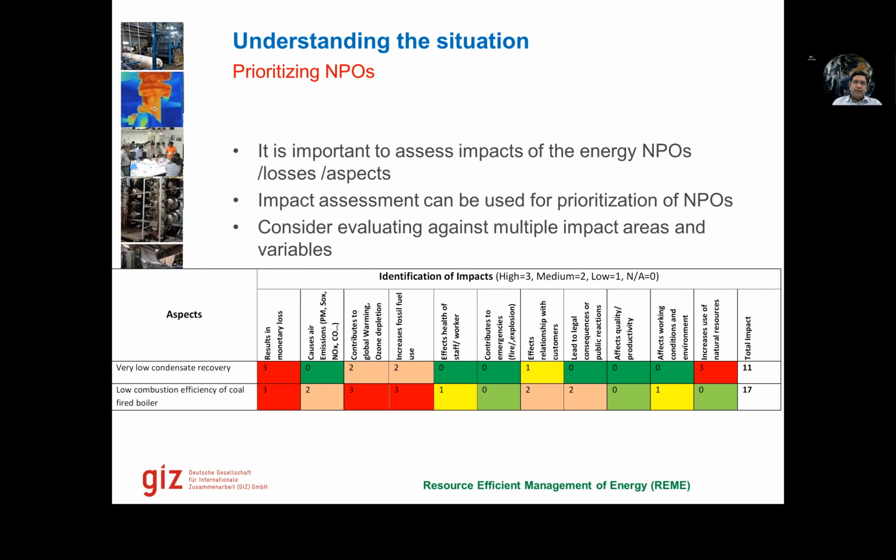It is very simple. Let's say we have a value of NOx coming in the sample, and we know that this NOx value is in either grams per cubic meter or ppm. What we need to do is estimate the total discharge volume of the flue gas. This would come in, for example, cubic meters per hour. And if we have a grams per cubic meter value for one of these, we multiply it with the cubic meter per hour value of flow. So we get the gram per hour discharge of NOx, CO, PM, sulfur oxides, for example, all these pollutants.